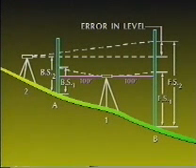The second setup should be where the back sight point A and the fore sight point B can be observed with minimal turning of the level. By setting the level a short distance from A, the fore sight and back sight are intentionally unbalanced. The unbalanced sight distances will exaggerate any error in the mechanical workings of the instrument.